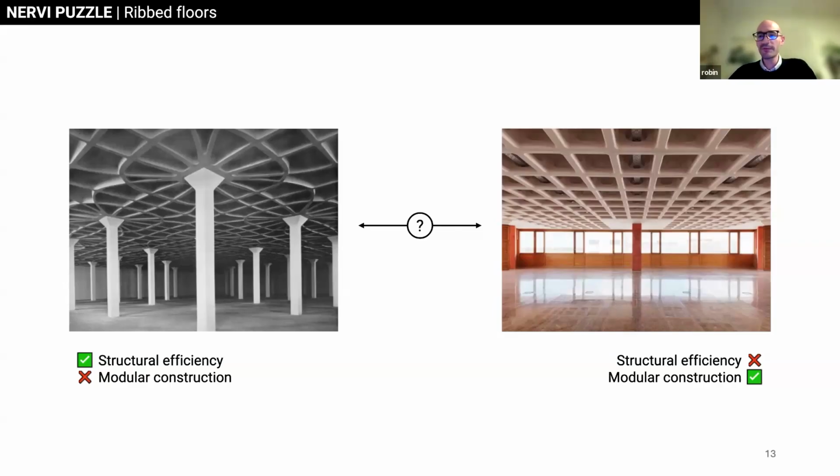But it doesn't follow the force flow of support conditions at all. You can see in that example that in here you would have a nice pole where all the beams come together. Here you need to have this big patch for local reinforcement, so you avoid, in a very practical manner, the column punching through the floor. So in terms of structural efficiency, that's not the best one.